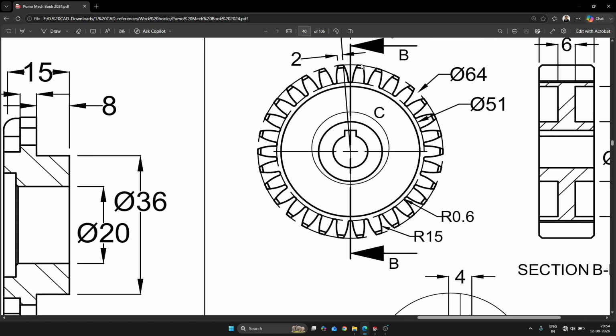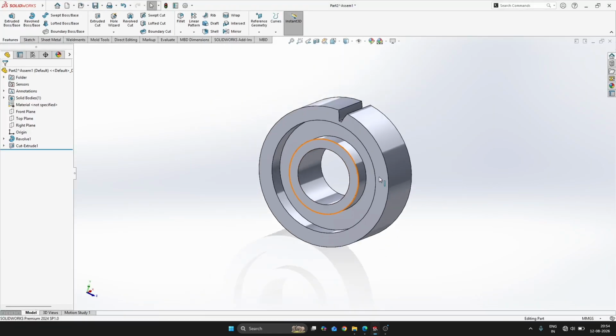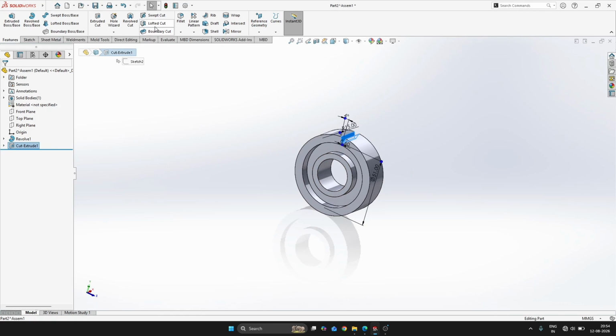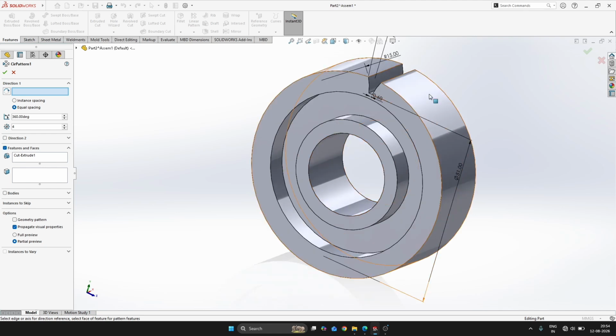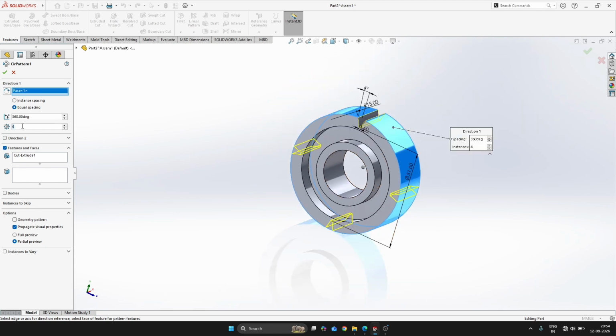I'll start from here. 1, 2, 3, 4, 5, 6, 7, 8, 9, 10, 11, 12, 13, 14, 15, 16, 17, 18, 19, 20, 21, 22, 23, 24, 25, 26, 27, 28, 29, 30. 30 teeth were given, right? So select this cut extrude, use circular pattern, select one circular reference, and update the instances value to 30.